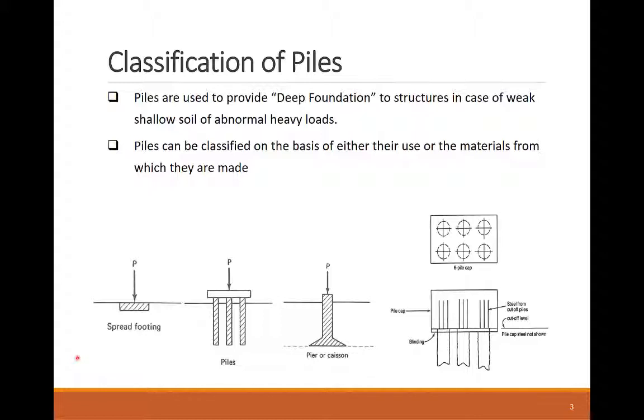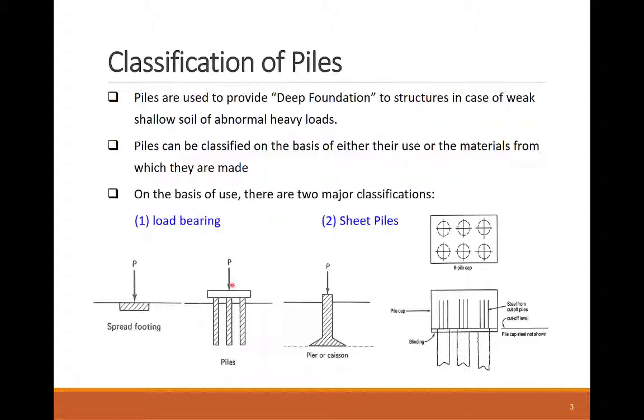A single building can have tens to hundreds of piles, where each three or more piles share a pile cap as an intermediate to distribute the load from part of the building to each pile under the cap. Deep foundation piles are also called load-bearing piles. There is another type called sheet piles, and they are mostly used to hold lateral soil load, not vertical structural load.